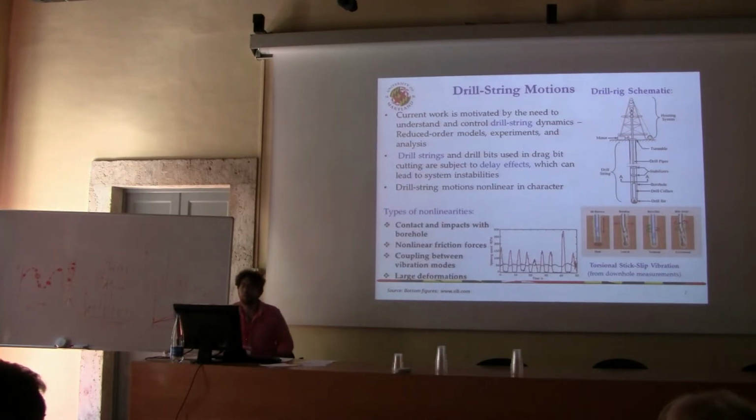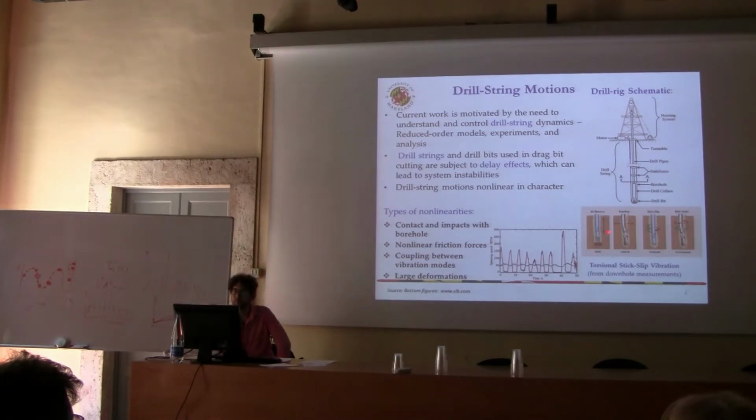You also have the different other modes. The axial motions, as the drill bit bounces off the surface, it's called a bit bounce. And you have bending motions, which Professor Spanos spent a considerable amount of time and effort in understanding lateral instabilities as well as how the bending motions affect the drill string dynamics itself. And this corresponds to torsional vibrations that I talked about.